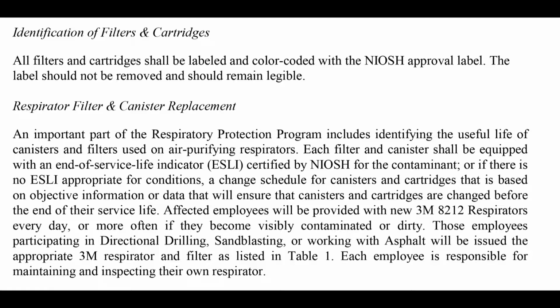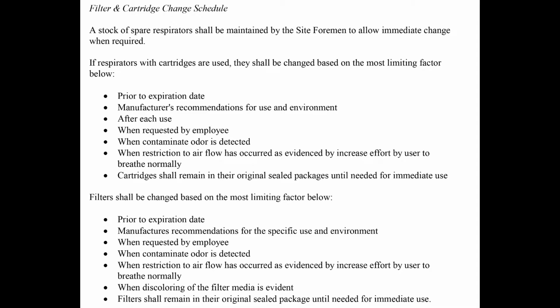Those employees participating in directional drilling, sandblasting, or working with asphalt will be issued the appropriate 3M respirator or filter as listed in Table 1. Each employee is responsible for maintaining and inspecting their own respirator. Filter and cartridge change schedule. A stock of spare respirators shall be maintained by the site foreman to allow immediate change when required.